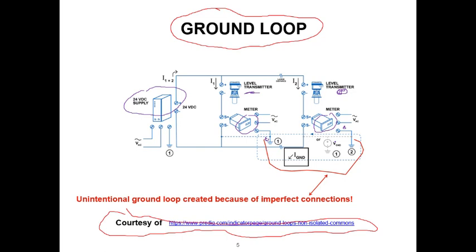Right? If you recall our work in the laboratory with the oscilloscope, we always had you connect the black scope clips, the ground clips, to the same ground point. And the reason is we wanted you to not have a ground loop, which can occur if you have it at two different points. So that's why we had to do that.